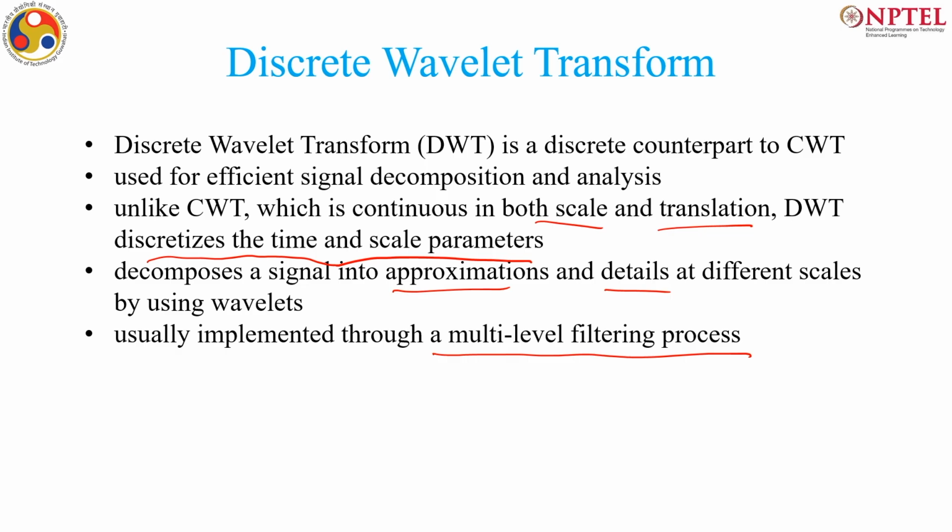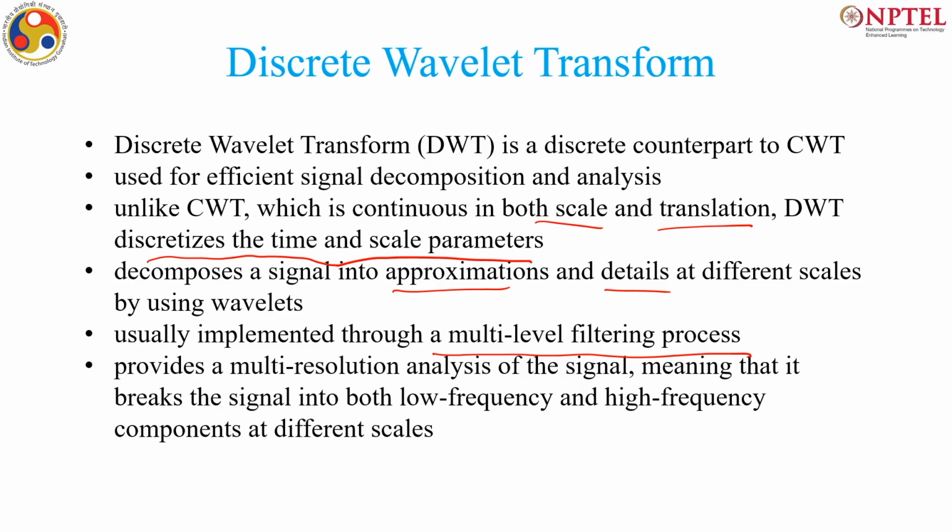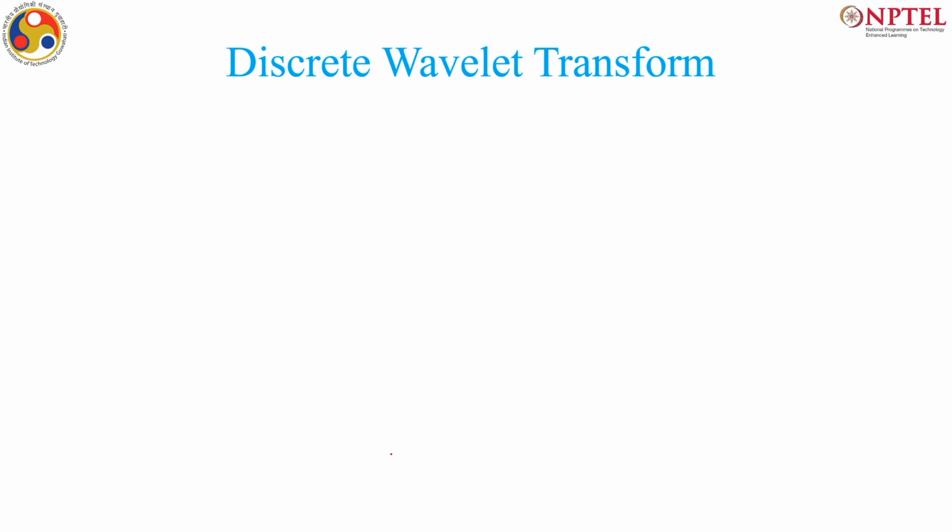So here concepts of your multi-resolution or multi-rate signal processing will be used, and that is what I am talking about. So it provides a multi-resolution analysis of the signal, that is it is breaking the signal into both low frequency and high frequency components at different scales.